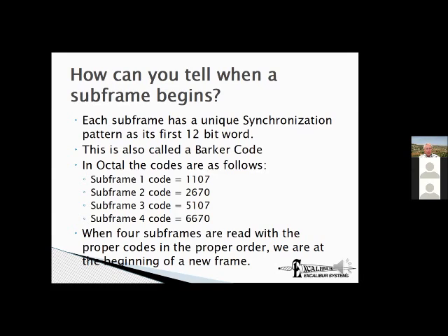Now, what happens is you start your card running, and the hardware of the card looks at each bit, and in each bit it checks each set of 12 bits. And remember, I don't even know where the beginning and the end of a word is. So the first bit that comes in, it reads from there the first 12 bits, and it says, "Are you 1107?" And if it's not, it throws out the first bit, adds the 13th bit, and now looks at this set of 12, 2 through 13. It says, "Are you 1107?" And so on. Eventually, it'll find an 1107.